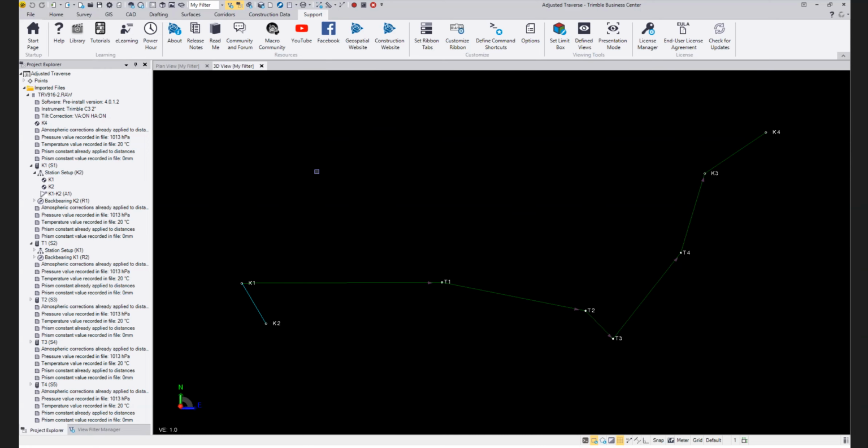There's also a 3D view available to you where I can turn my observations and actually look from the side. Again, if I had many side shot observations that are measurements for topo data, and I incorrectly failed to adjust my rod height correctly in the instrument when I was making my measurements, you may see a vertical discontinuity or vertical jump in your data here that could be caught by looking at it in this viewer mode and looking at it in 3D.